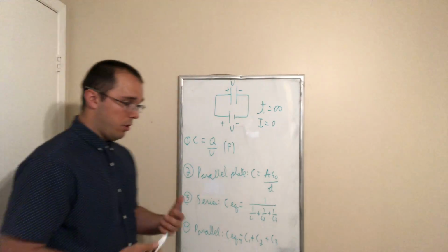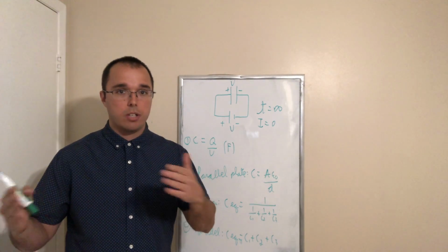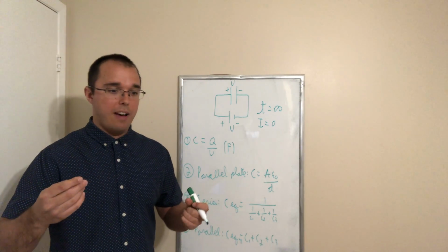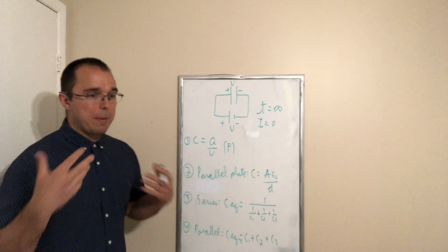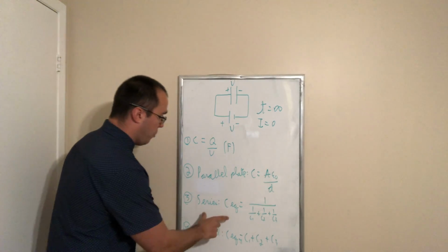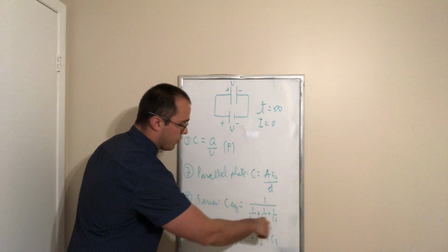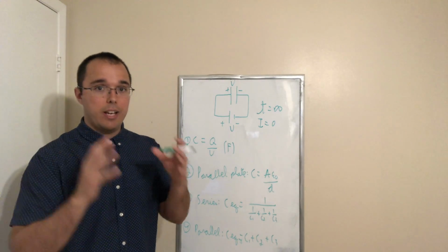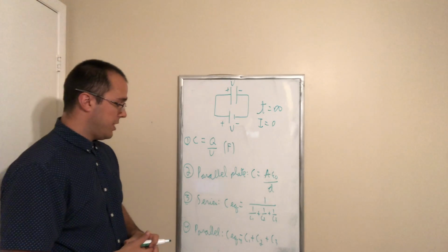The third point is that just like in series and parallel circuits using resistors, there will be a way to have an equivalent capacitor. So if we have three capacitors in series, for example, and we want to find the equivalent capacitor, we use this formula. It is really similar to the parallel resistor equation. Actually, it is the same. We just replace the resistance with the capacitance.